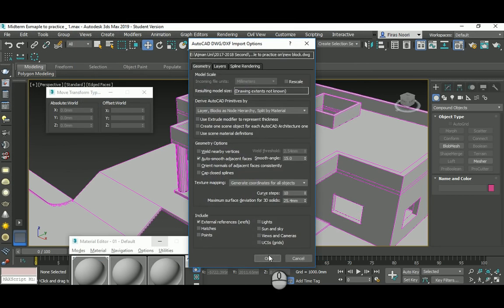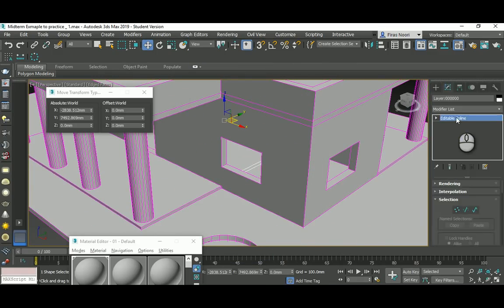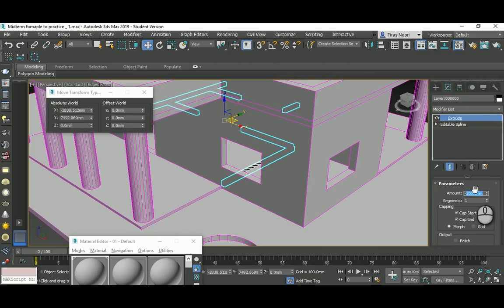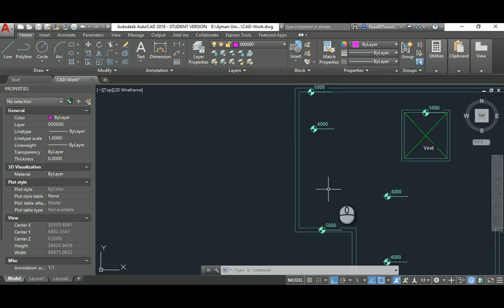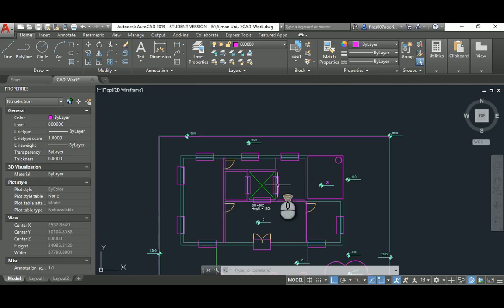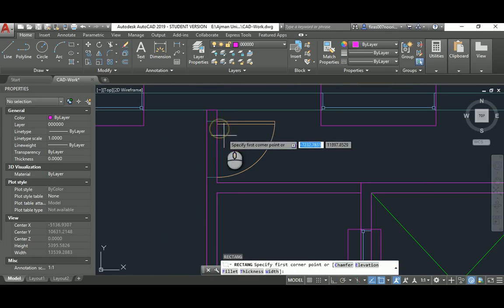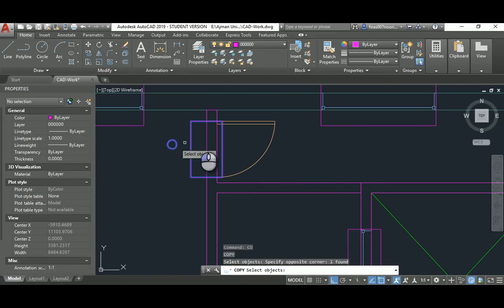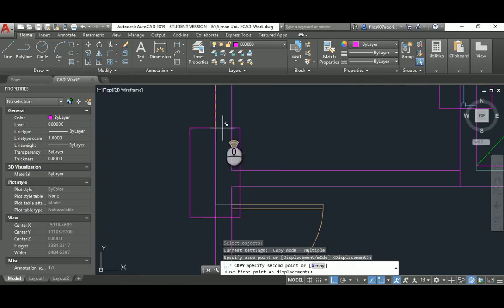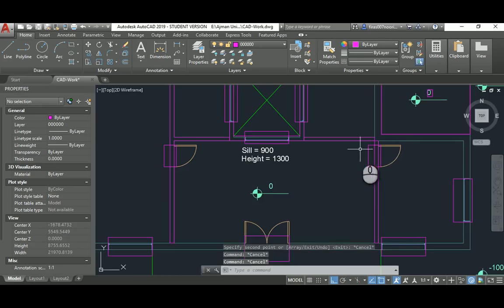So yep, it's on 0, 0. So just give it an extrude, and the extrude should be 3800, which is the difference between the 0 to the 4000 minus the thickness of the slab, which is 200. So 4000 minus 200, and you can do the math. Now rectangle, and let's do this door, the inner opening, and this one, and this one, and same right block.